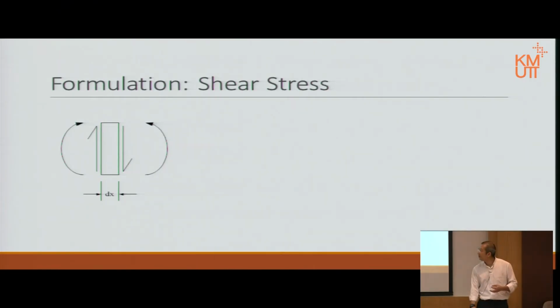Of course, we have the bending moment and the shear on one side. When we move by dx, the value of shear and the value of bending moment have changed. Therefore, it becomes the shear plus the change, and of course the bending moment plus the change.